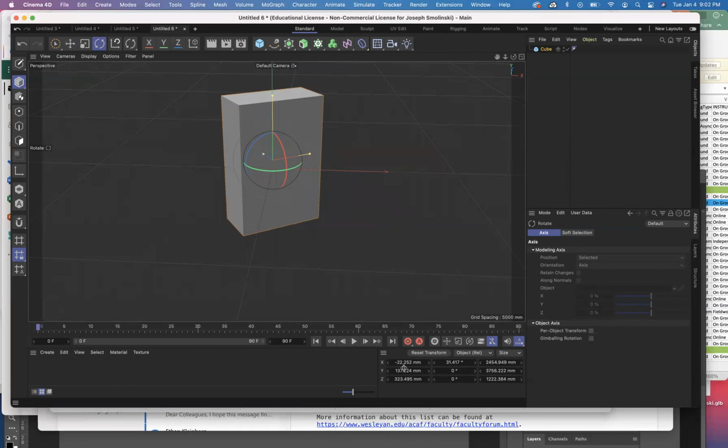Finally, you can make any adjustments down here below. The first one is position, the second one is scale, and then rotation. All right. So if I want to zero this back to the 0 marker, I can just hit 0, 0, 0, return, and it'll snap back to that 0 position. I've moved it a few degrees along the Y, 31.4. If I zero this back out, it will bring it back to that position as well.